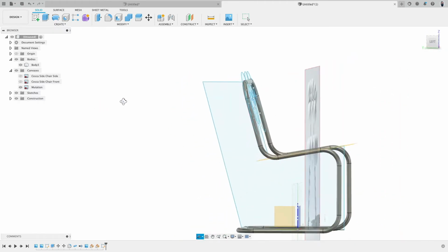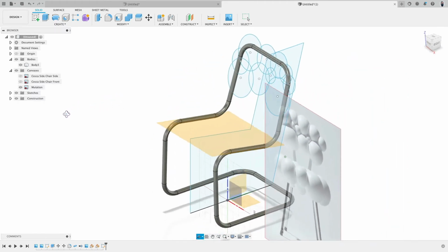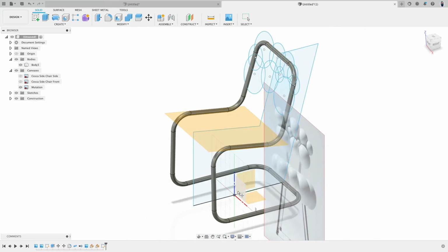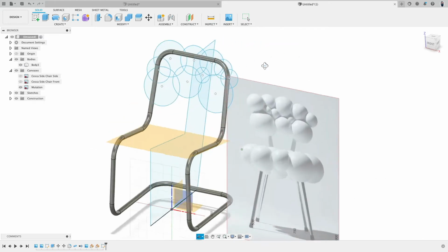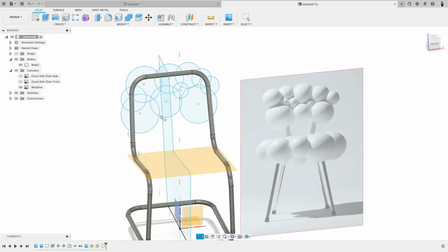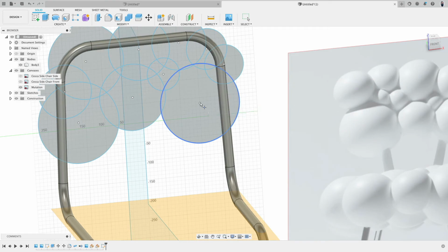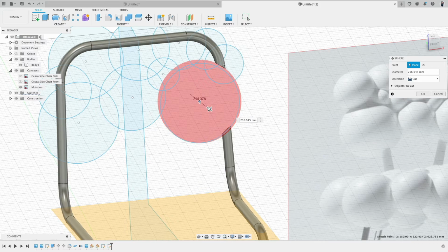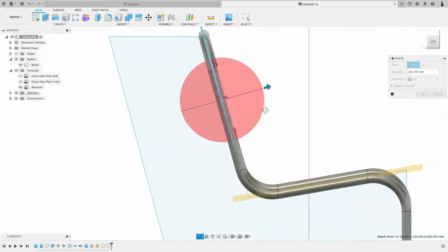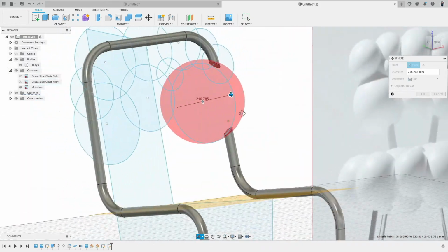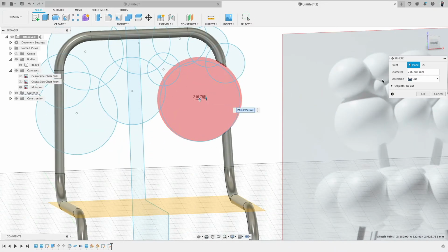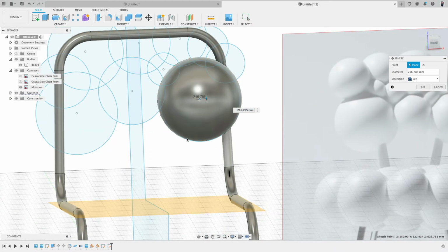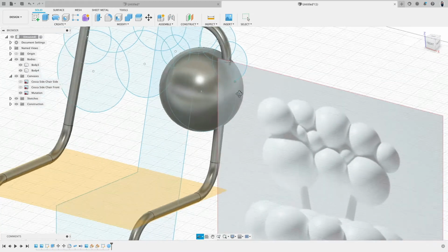Then we go to sphere, and we would like to position the sphere in 3D space. And you see here, we can put this onto these planes, or actually, that's the reason why we made the sketch. I can position this on this circle. Then I click, and then I drag this and make sure at one point, now this looks pretty good. So currently what's happening, this is cutting. We don't want to join because that fuses it to the pipe. We just go new body and okay.